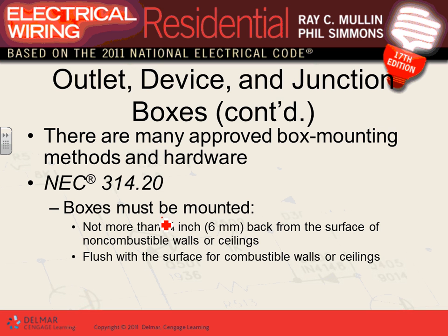Boxes, when you mount the boxes, this is for project managers. A quarter of an inch back from the surface of non-combustible. You can set it back, if it's non-combustible like sheetrock, up to a quarter inch and it's okay. If it's combustible like wood, they want you to flush it.